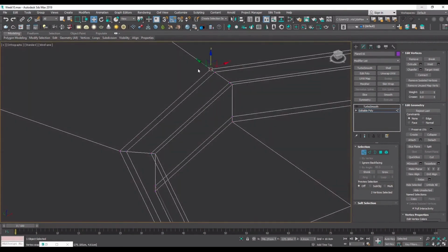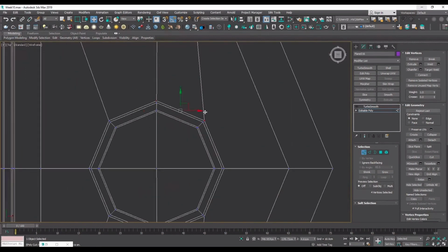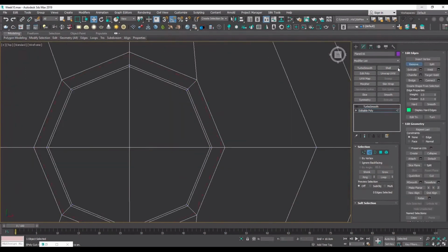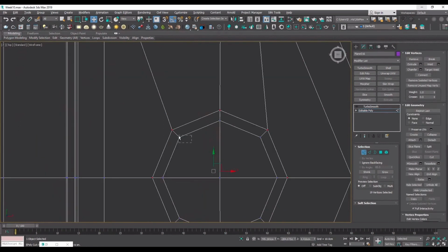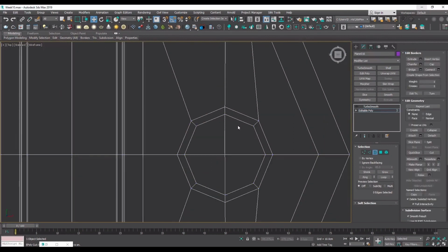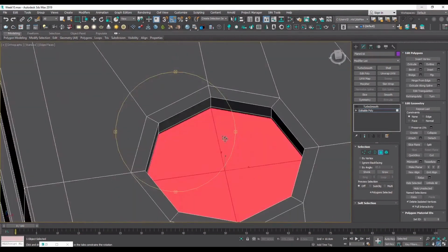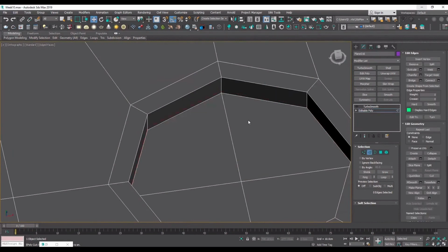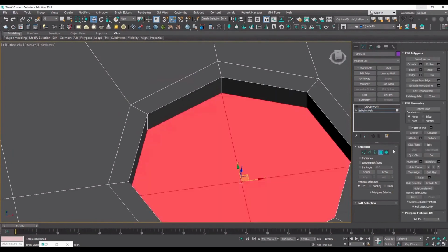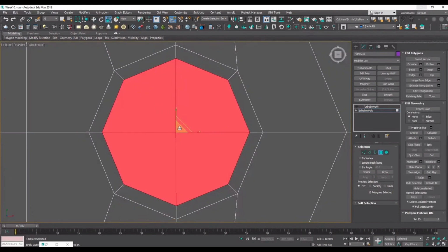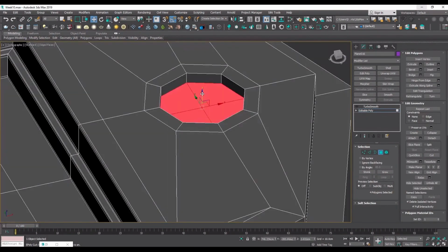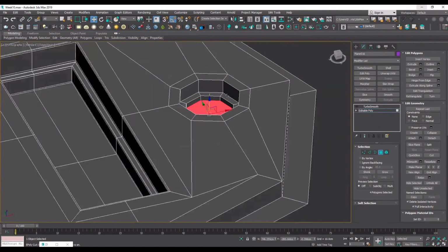Then I will get rid of the edge loops that we had on the upper part, and then select the main safe loop. Now, after I selected the loop manually, I have to use the weld command to connect them with the other vertices. So this way we can properly move them and there's no problem anymore. Now, in order to get back to where we actually left off, we should repeat our process, reposition, and then extrude our mesh down as we did in the past, get an inner inset as we did in the past, and put it where it actually was before.